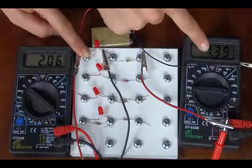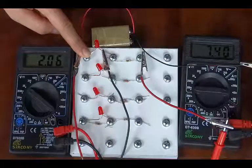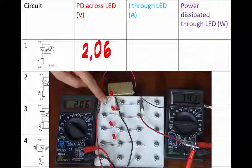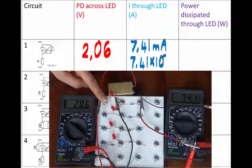This one's voltage, that one's current strength. So we see that the voltage across the LED in circuit 1 is 2,06 volts. And the current strength through the main part of the circuit, which is also through the LED, is 7,41 milliamperes, which is 7,41 times 10 to the power minus 3 amperes. And we can see the unit there is in amperes.